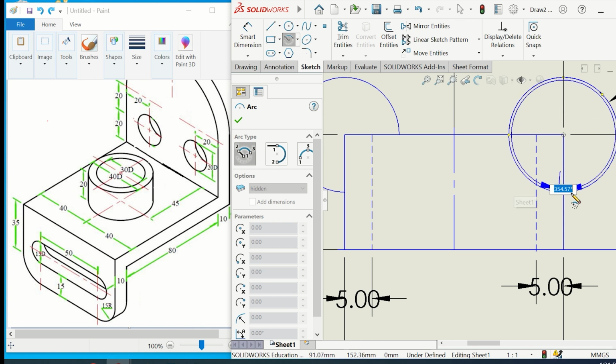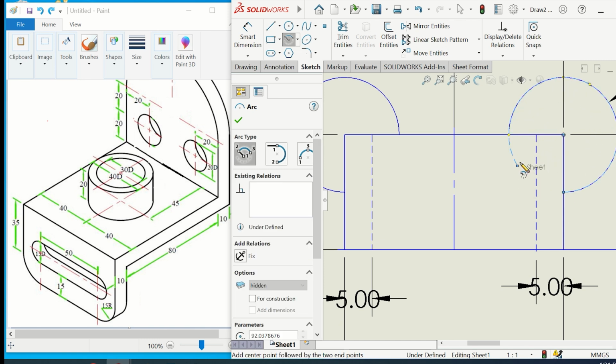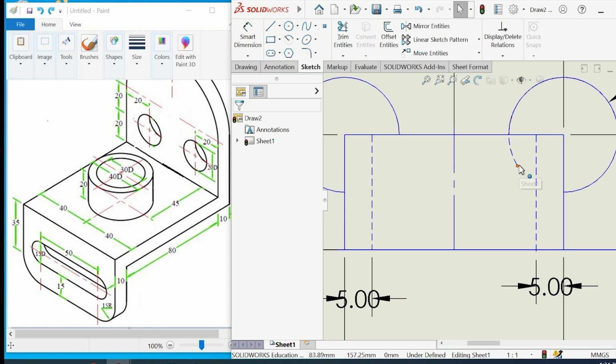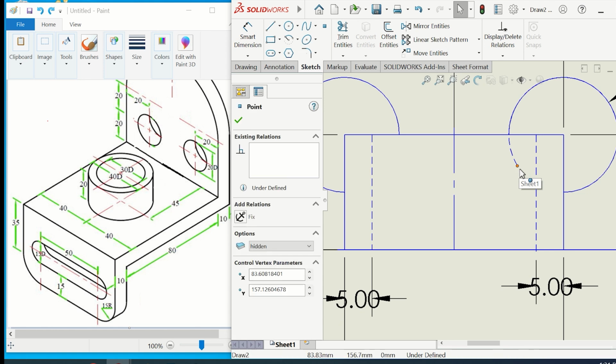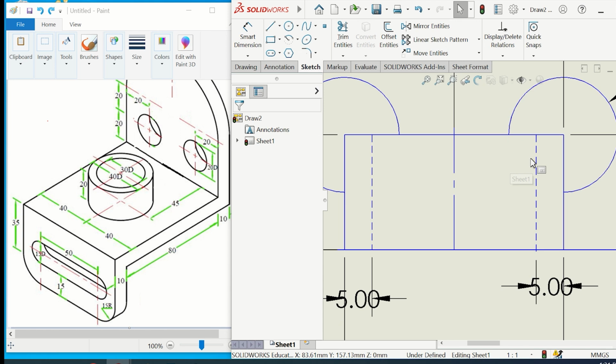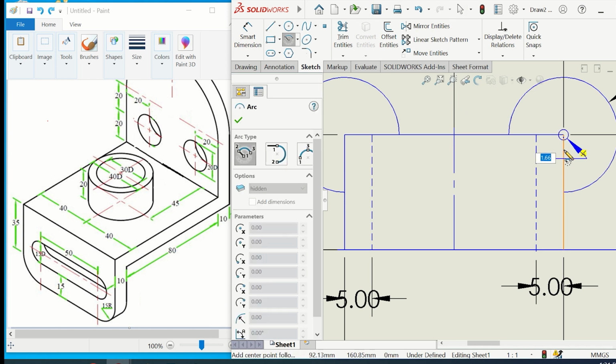Okay, so I wanted to draw this. So I rotated my mouse till SolidWorks started to draw starting from here. Okay, I clicked here by accident. Okay, fine, I can click, oh no, undo, Control Z. I'm going to draw it again. Arc, center point arc, start from here. I click here to start from here.